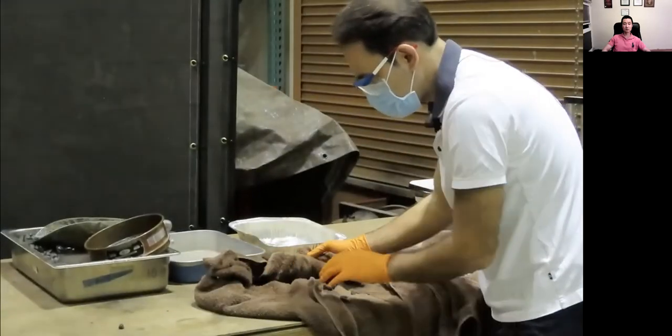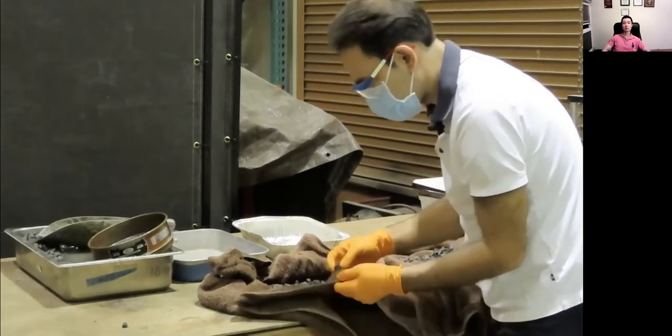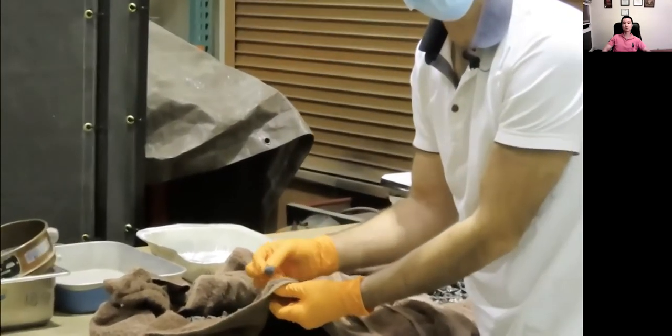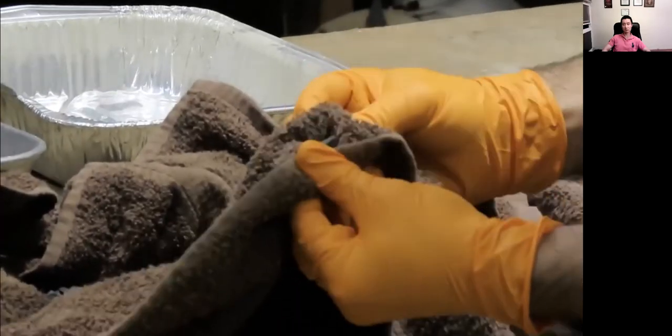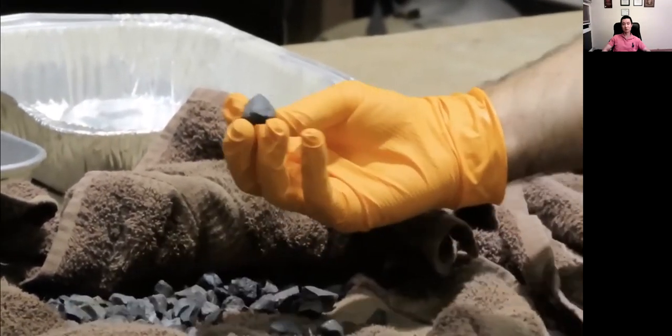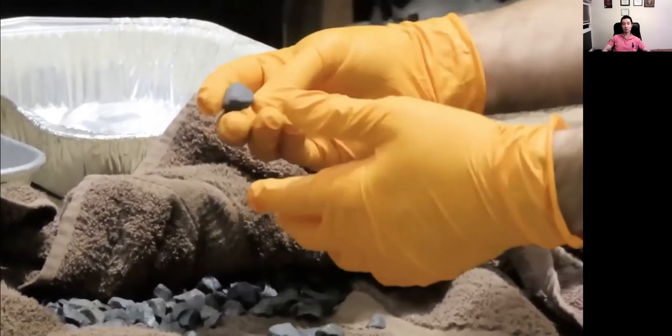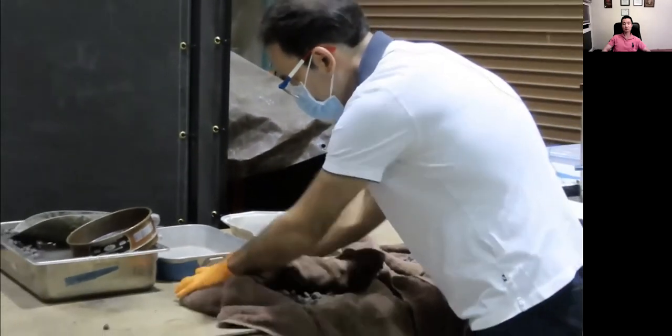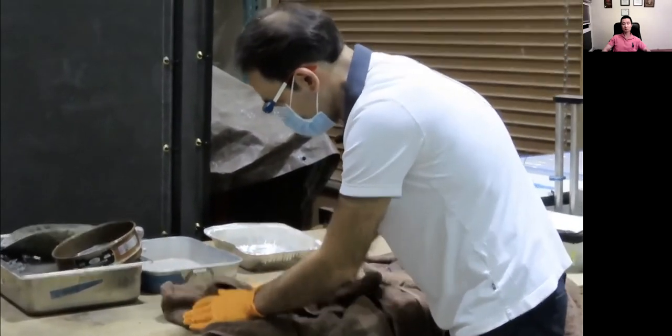If you want to see that the aggregate is dry enough, you can grab one particle of your coarse aggregate and try your best to dry the surface and see the color and compare it with the rest of them to make sure that all of them uniformly has dry surface. So it should be something like this. It is not shiny anymore. So I try to have all of the coarse aggregate particles like this.